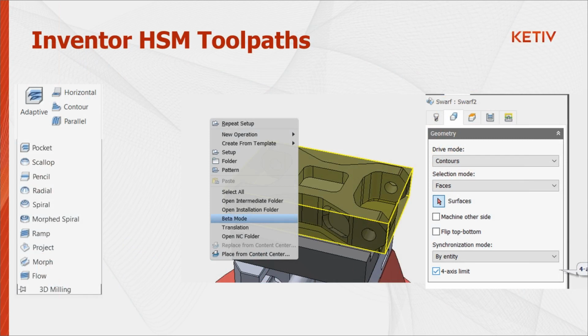And so here we have some of the Inventor HSM toolpaths, right? When people automatically think 5-axis toolpaths, they think, okay, you go to the multi-axis tab, you hit the drop down, and you just see those 2 or 3 toolpaths that are included under the multi-axis tab. But what a lot of people don't know is that some of the 3D toolpaths already have 5-axis capabilities, right?